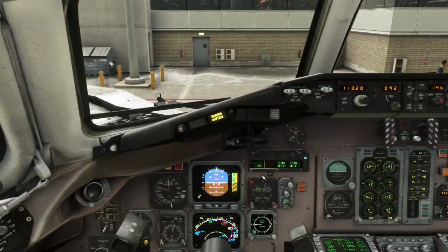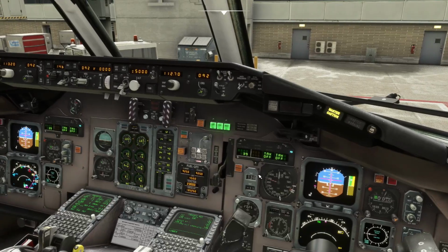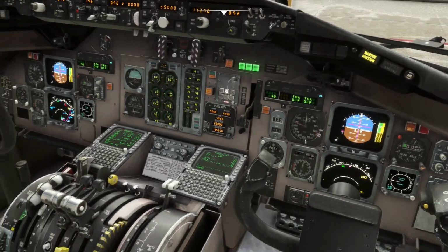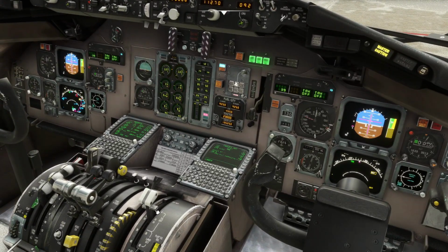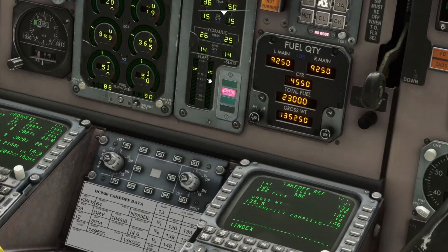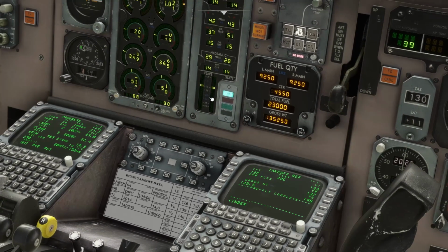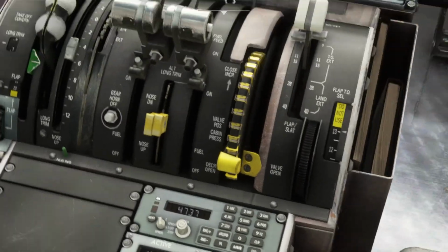Now a couple things we can do here. Crossing right 4 left at Charlie. We can set the flaps to the dial flap position. Roger, crossing 4 left at Charlie, JetBlue 1755. That's 2 notches. And we need to look for flaps 13 degrees, so that's somewhere in between there. Yeah, TO. We set 13. So that's just about right.